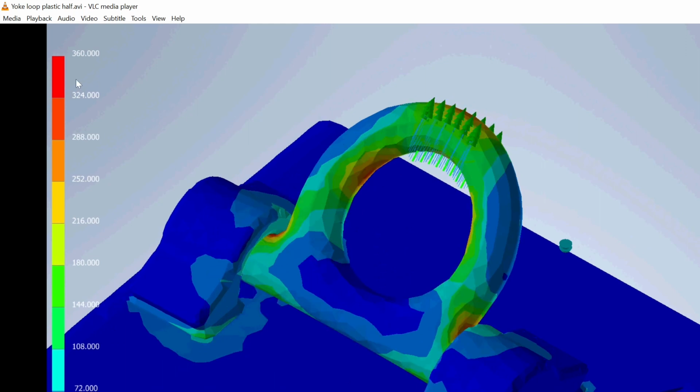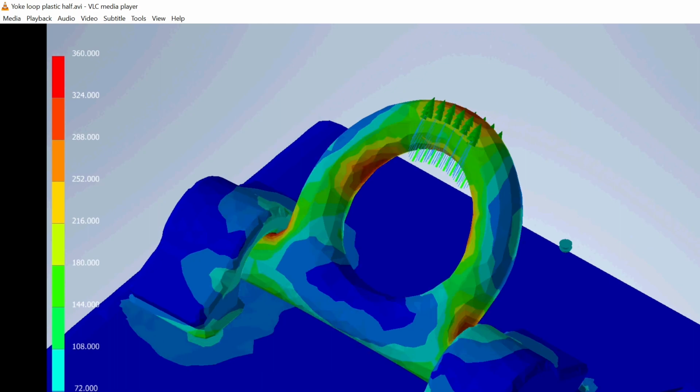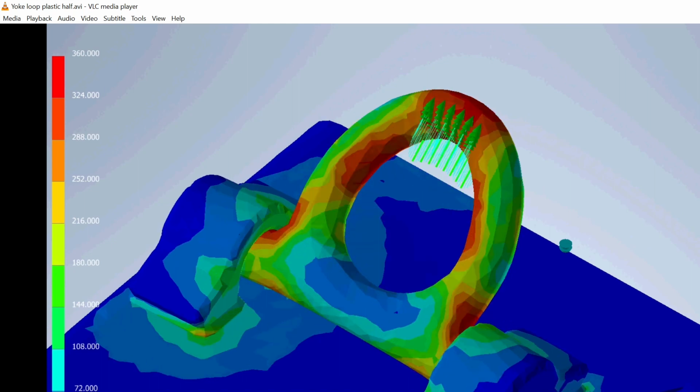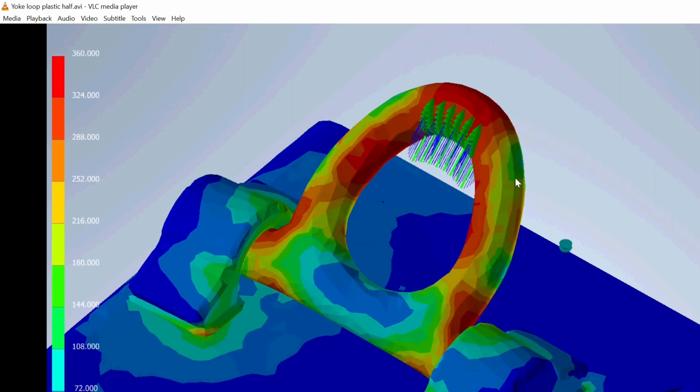That's where the limits begin to get triggered, and that would not pass. If you have a plastic simulation, the stresses redistribute, and you can find that the actual structural failure happens around twice the load.